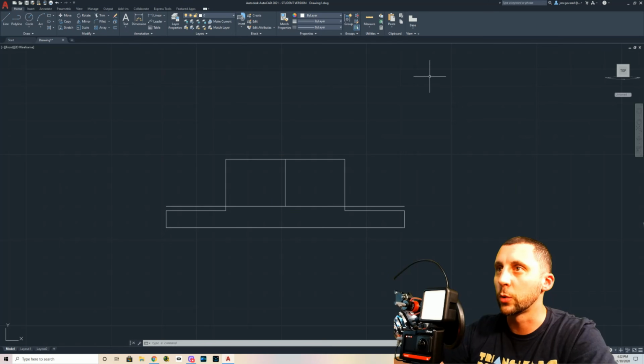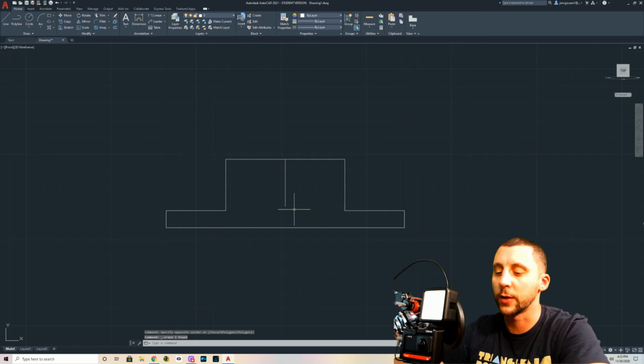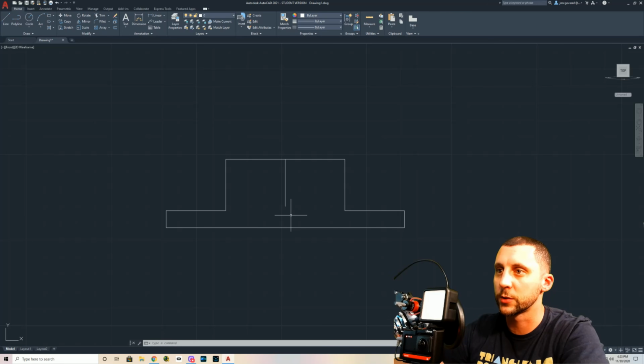3/8 becomes 3/16. So what I'm going to do is I'm going to take a line here, and I'm actually going to get rid of this line. That was just to find where this line point ends right here. I call those dummy lines in all my other plans and videos that I do. A dummy line usually just gets erased. It's just there to show you something else, or the size of something else or the position of something else.